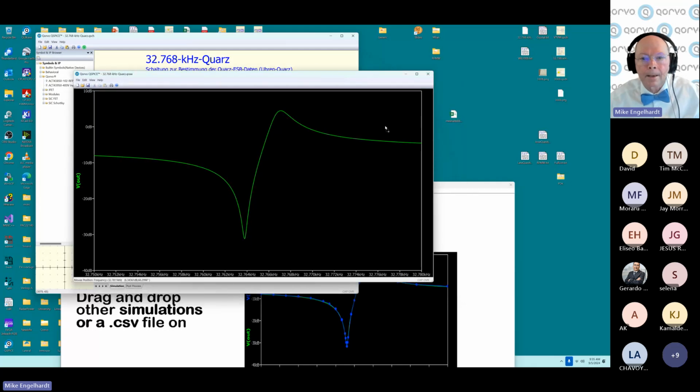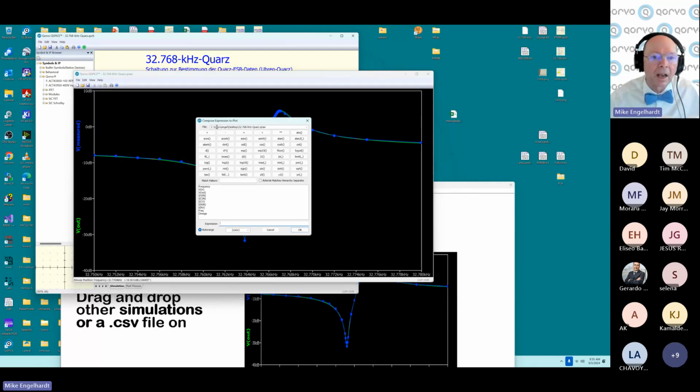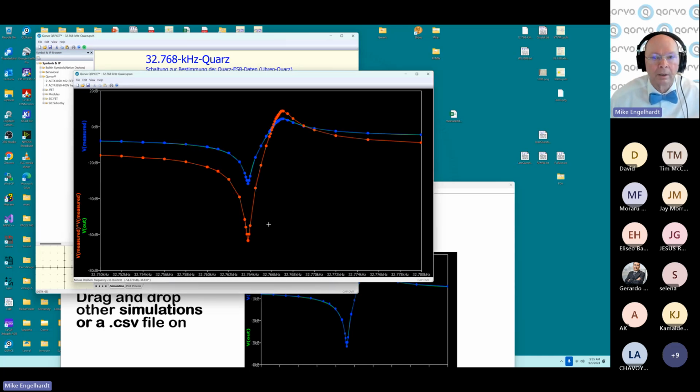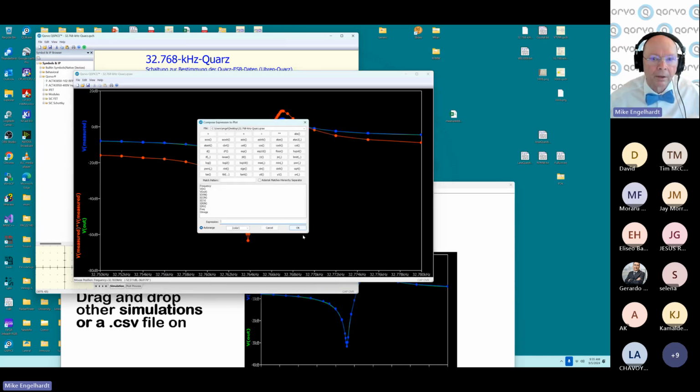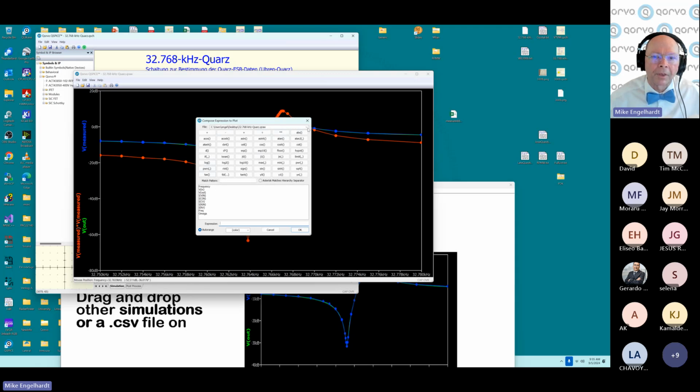Here it is. If you add a waveform trace, now you have this thing about you're going to plot expressions, but you can plot expressions from all the different files. Let's plot that V measured squared. So the waveform editor here, the thing that lets you compose expressions of waveform data, is more complicated.